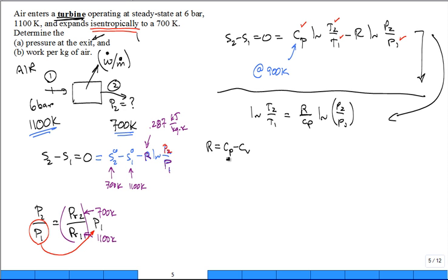Okay, let's quickly rederive that equation. How did we derive that equation? Is H equal to U plus PV for an ideal gas as well as any other substance? Is H a function of temperature only? Is U a function of temperature only? PV, is that equal to RT for an ideal gas? PV is equal to RT for an ideal gas, right?